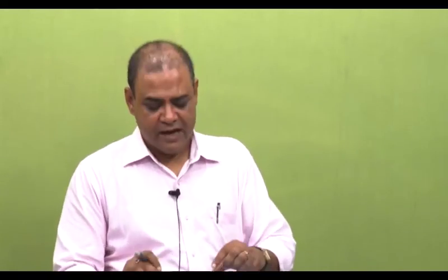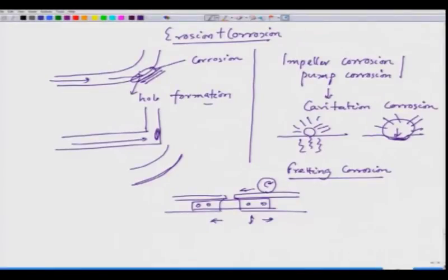When this fretting happens, since they are tightened, there could be a formation of oxides at the interface between the fish plate and the steel of the rail. Because of this fretting action, oxide forms on these two surfaces, and there is a small amplitude vibration under load because the train is running on it. So, then these ridges might get dislodged.